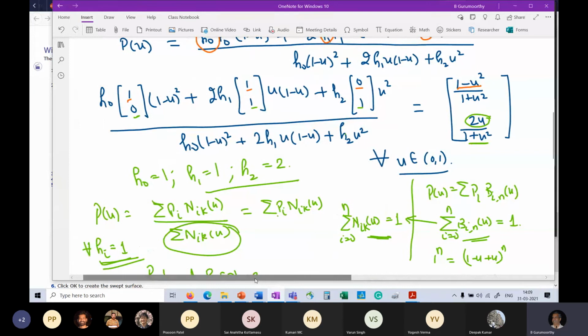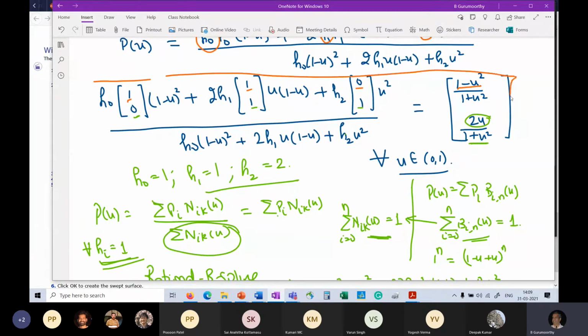Right, so if you see the box that I'm drawing now, this is one quadratic rational B-spline curve on the left-hand side. Okay, so for a given set of control points, (1, 0), (1, 1), (0, 1). This is something that we had obtained from just what we know about the spline curves, and we stayed with the same. And the only thing I have done around that is to write down the rational spline expression.